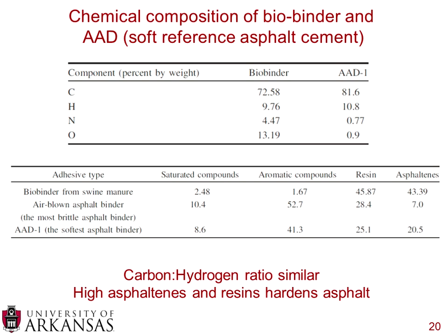Now I could go off on a 10-minute rant about the different components of asphalt cement, which include saturated compounds, aromatic compounds, resins, and asphaltenes. But I think if you just all agree that these are the 4 molecules that are the building blocks of asphalt cement, we can go from there. So if you break down asphalt cement into different molecules, the vast majority of it is saturated, aromatic, resin, or asphaltene. Those are the SARA, S-A-R-A components.